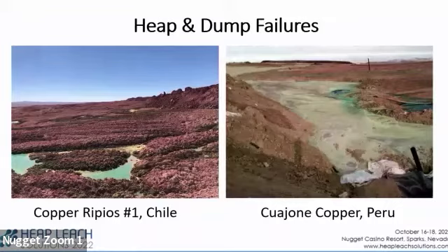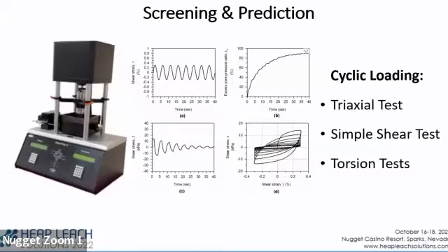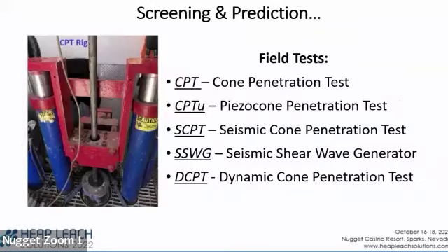And so, in fact, it's chemically still active because the pH of this stuff's pretty low. So trying to recreate this in the laboratory, for tailings, it's pretty good because tailings really is just kind of fine sand. But for leached ore, especially if it's an in situ heap you're trying to evaluate, I generally recommend against trying to get into cyclic testing, even though it's fantastic data. But if you don't have great samples, why spend all, and these are expensive tests, and you're going to ship this somewhere. You're going to ship it to UC Berkeley in California or U of Texas, Austin, or someplace like that. You're not going to do this even in Chile, where they have fantastic facilities. Maybe a little, although we've had terrible luck with them.